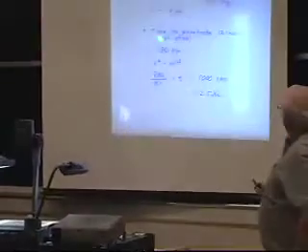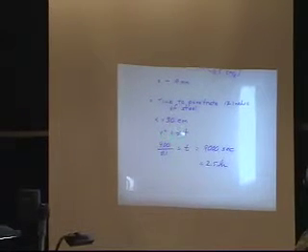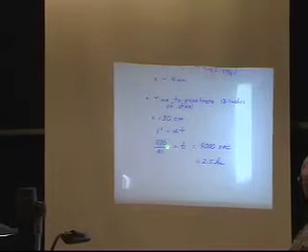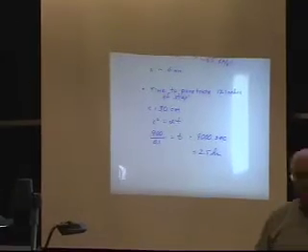We said, we might as well go through this, since you were here. Time to penetrate 12 inches of steel, 30 centimeters, x squared is alpha t, 900 divided by a tenth, 9,000 seconds. It takes 2.5 hours for the inside to start to warm up if you put a great big piece of steel that's 33 inches diameter into a furnace.